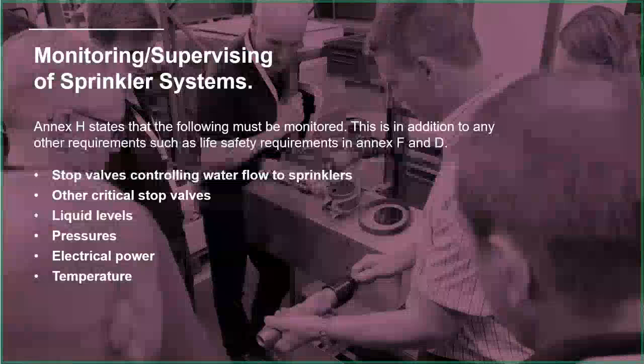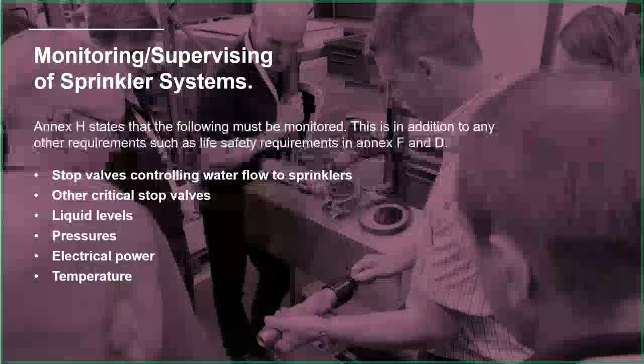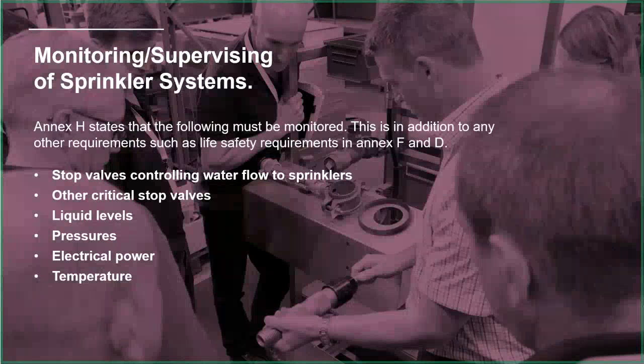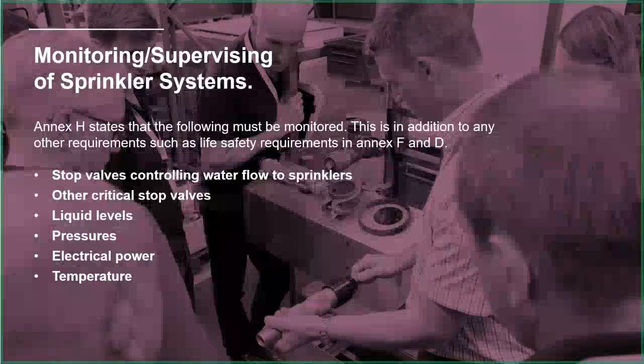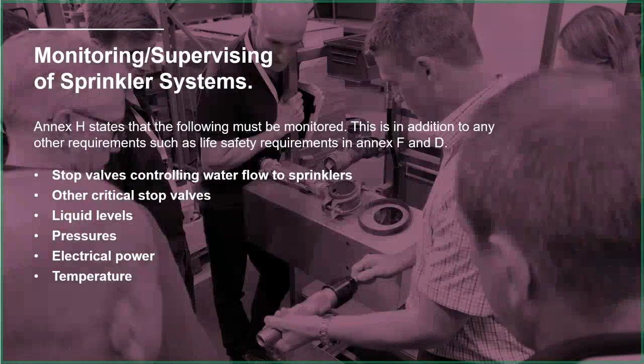Stop valves controlling water flow to sprinklers. So any stop valve which is going to be controlling water to sprinklers should be monitored. Other critical stop valves. What that means is other valves that are important for the sprinkler activation. So, for example, the infill to a tank may not be vital, because if you've got a full capacity tank, then you're not actually relying on the infill. But if you've got a reduced capacity tank, then any valve on the infill is going to be a critical valve.